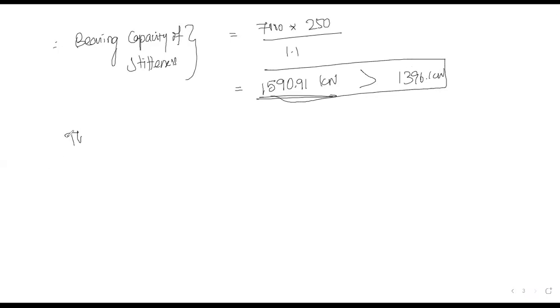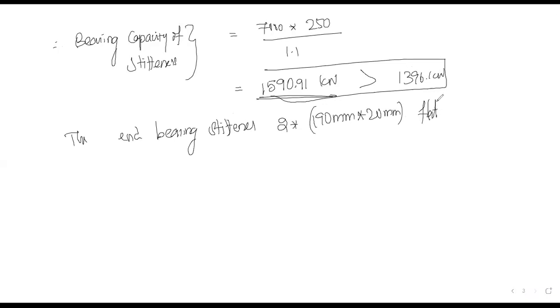That is, the end bearing stiffener, 2 into 190 mm by 20 mm flat, is safe to transfer the bearing forces.